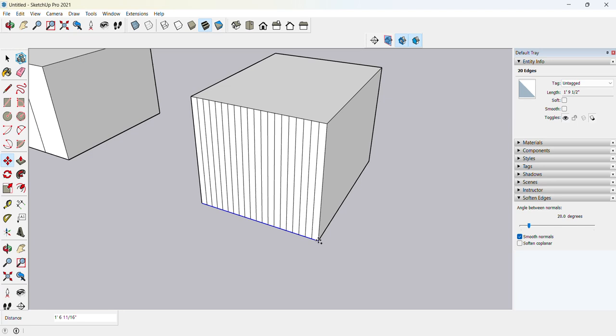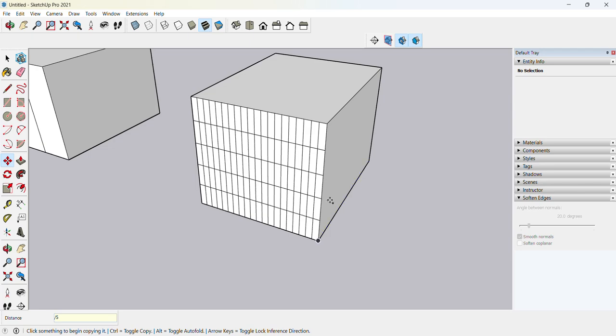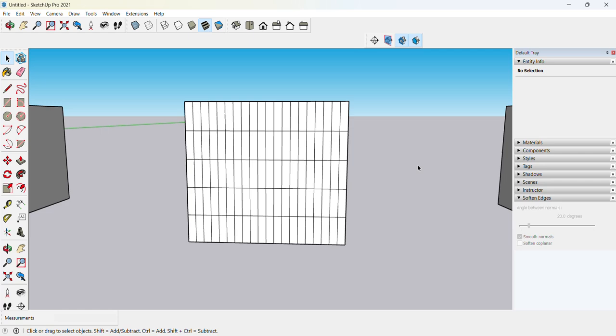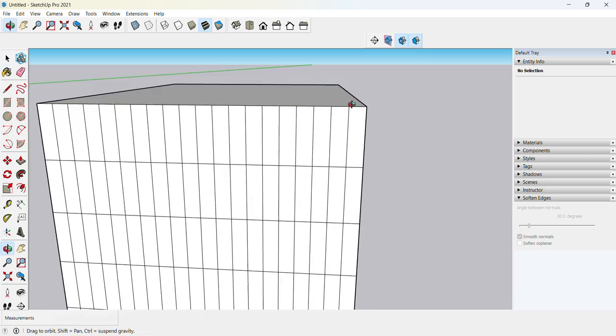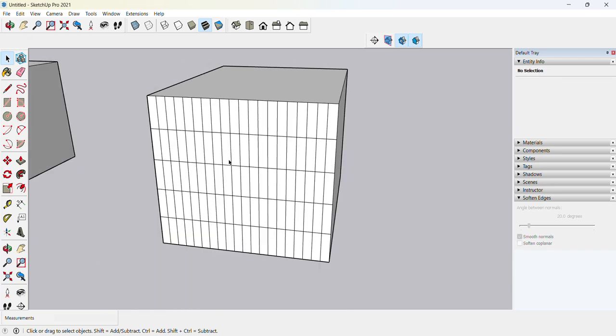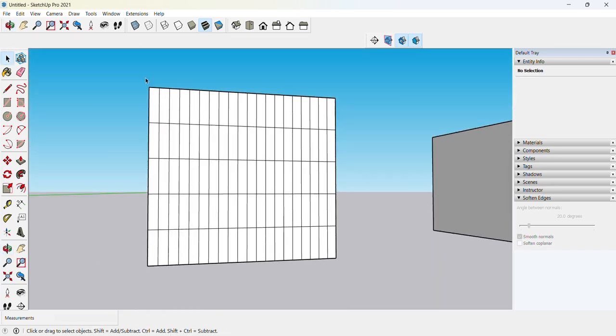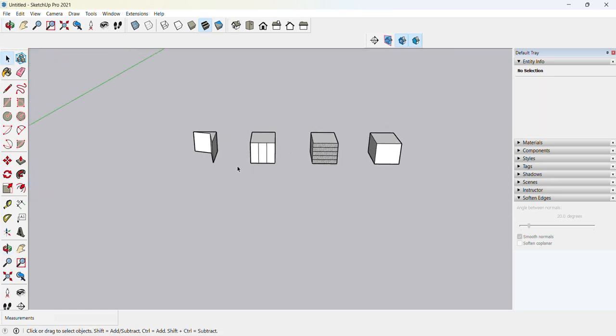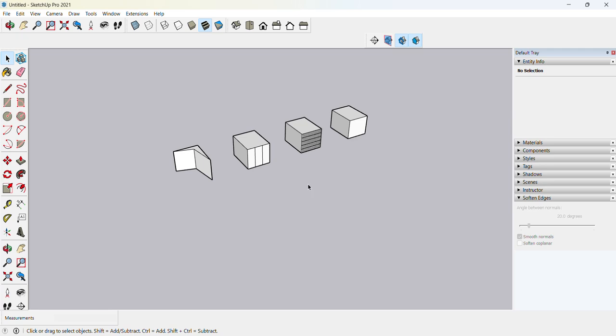Now here I am giving the division symbol because here we are doing a division, right? So for that I am giving division by 5. Enter. See how simply I divide a complete portion. If you want to divide all these portions by segment like this, one by one, then it takes more time. So it was the reason I select all the segments, all elements at a time. Okay. So this is our complete copy, move, push pull and same as well divide.